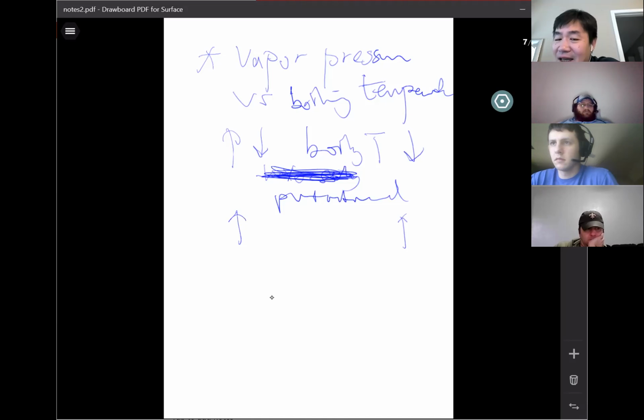When you design a fluid device, you make sure the pressure is not too low. It's not necessary everywhere, but you need to find the minimum pressure point in your design, in your device. Make sure the minimum pressure point is not too low, otherwise cavitation might happen due to that. So that's another topic.